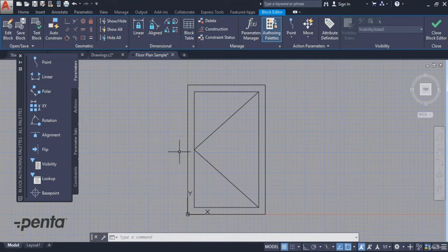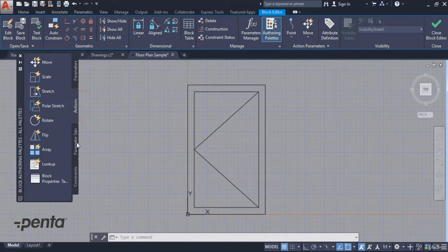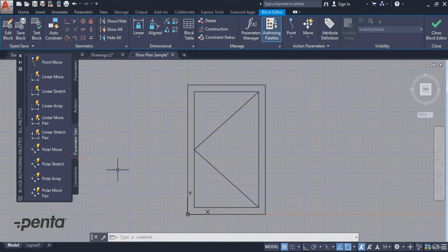Here you can create dynamic blocks. What's a dynamic block? For example, if a door has more than one measure, we don't have to create a block for each measure. This is actually a very comprehensive topic. Here we can have multiple objects with different measures combined into a single block. Thus, we can comfortably create more than one object. Of course, we can change all of these by using parameters, actions, and parameter sets.